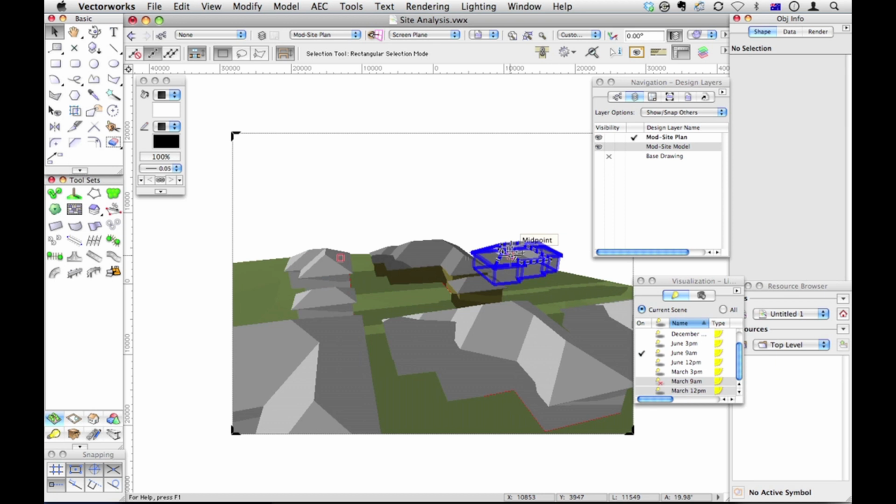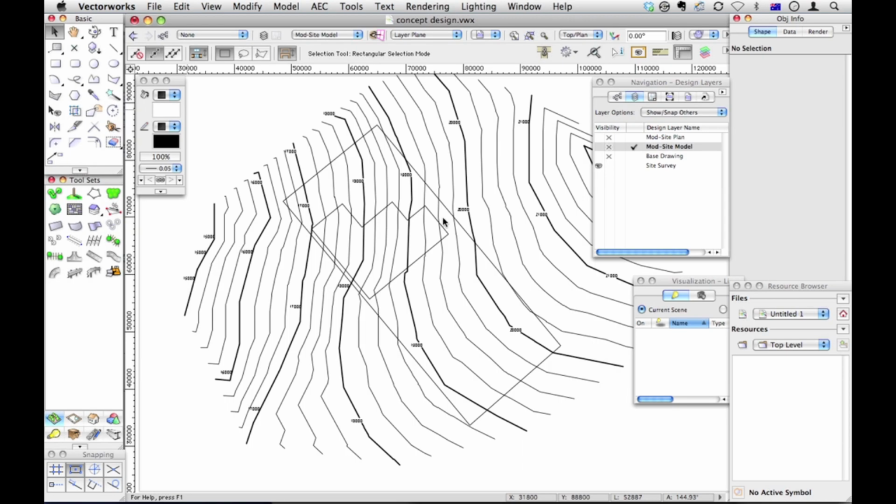So we need some site model information so that we can create what Vectorworks calls a site model. A site model can be created from spot levels or from contours. It takes the 3D data and it uses some mathematics to create this three-dimensional form, which we can then manipulate, we can count, schedule, we can do cut and fill calculations on it, and so on. There are several ways to create a site model, but each one has the same problem. We need 3D information. You could import your survey drawing, the site model from the surveyor, with 3D polygons, and that would allow us to create these 3D objects into a site model.